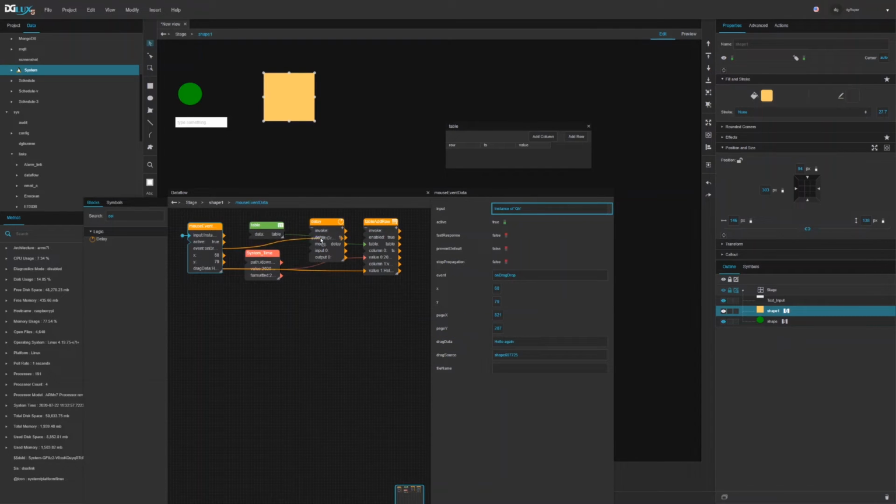So I'm going to use a delay block, and event will go into input, output go to invoke. And delay, I'm going to need a very tiny delay, just 0.2 seconds, like this. And since I already had an event there, of course it fired and gave me my first value, which is fine.